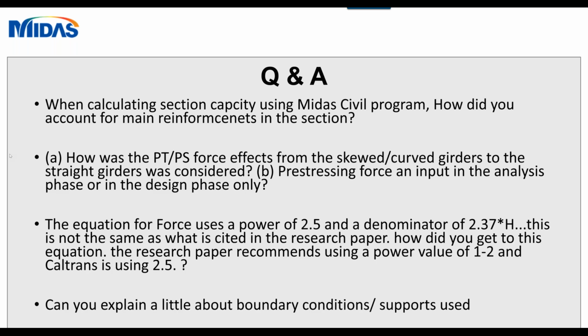And the other part is pre-stressing force input. I use the pre-stressing force as an input; the program didn't design the pre-stressing force. So it's kind of an iteration thing. I try a pre-stressing force and see how it works, and then I increase or decrease accordingly.